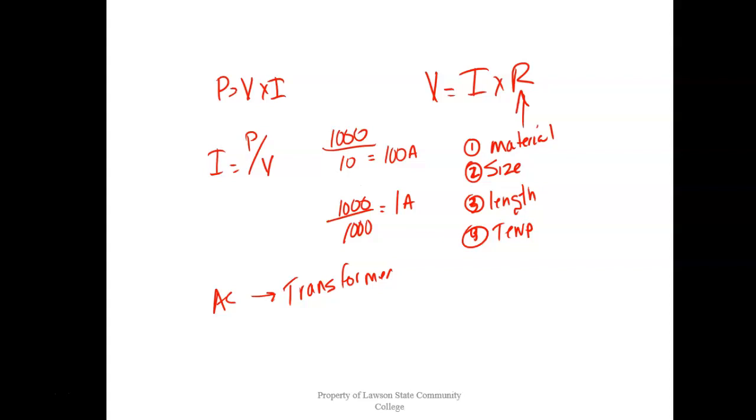So what they do to combine copper with aluminum is they put a paste on it. It's an antioxidant paste. If you go up where the downdrops from your house are aluminum, and you were to take that off, don't do that, you'd see there's a goop that looks like grease wrapped around it. That's actually inside the crimp where they go from the aluminum on the power lines over to the copper on your line.